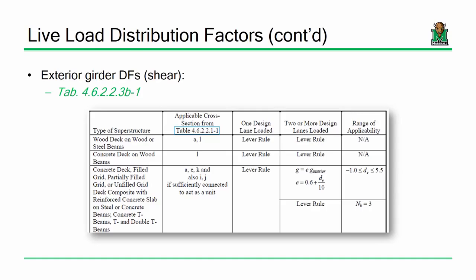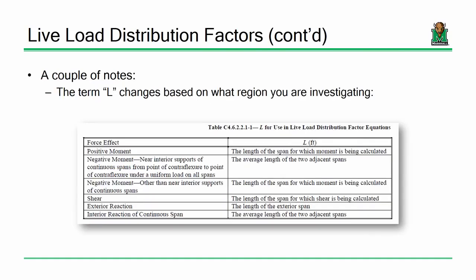All right. So far, so good? All right. This is just a couple notes. The term L, I say L is the span length, but you've got to be careful with that. For instance, if you're dealing with a two-span bridge where one span's 90 feet and the other span's 150 feet, what's L? Okay? So if you're in positive bending regions, L is just whatever span you're interested in. But if you're in negative bending regions, let's say around the pier, you take the average of L. Okay? Make sense? It's all about just details and making sure what's going on. Some of these rules seem a little quirky and a little strange. Again, goes back to the empirical approach, taking a massive pile of data, trying to fit an equation that represents that data.